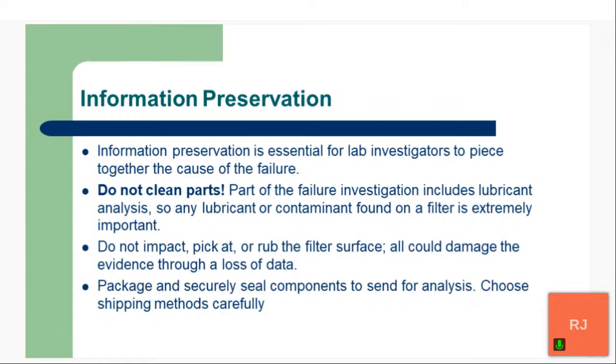A big thing, we talked a little bit about it before, but it's information preservation. So we wanted to stress these points again. Information preservation is essential for the lab investigation to put together the cause of the failure. If the parts are cleaned, we're not going to get all the information that we need to put together that high value report for the effort you're going through to collect the filter or the failed component. So as we mentioned, we don't want to clean those parts. We're going to wash off evidence, as Rich mentioned, and get rid of that evidence. Without that evidence, it makes the job of the investigators much, much harder.